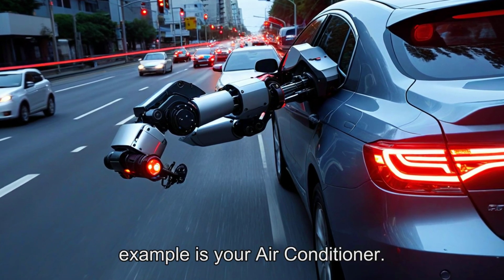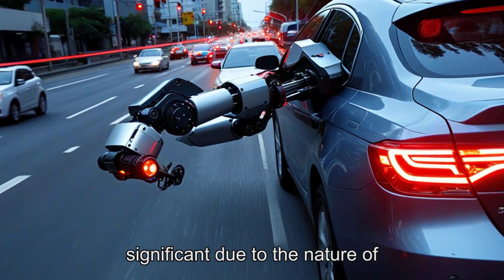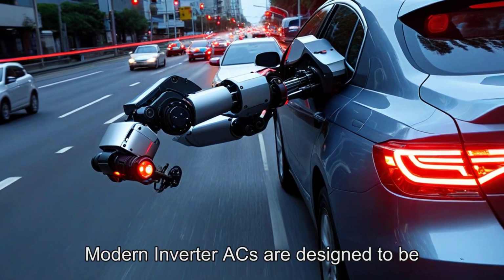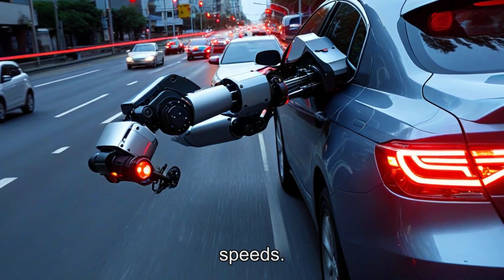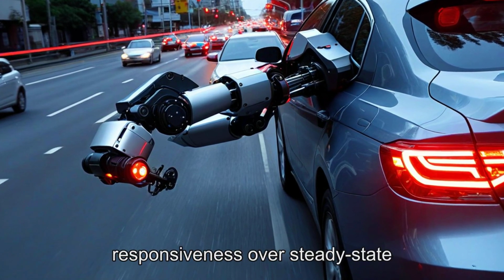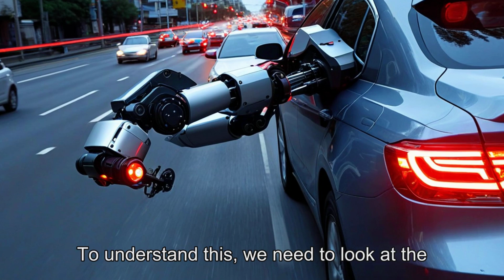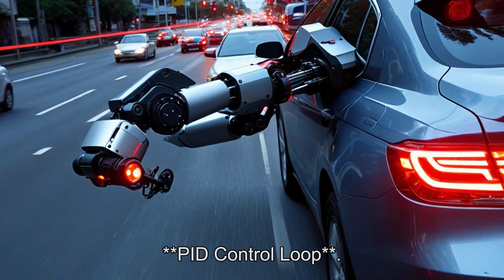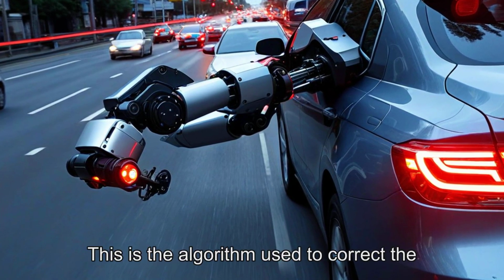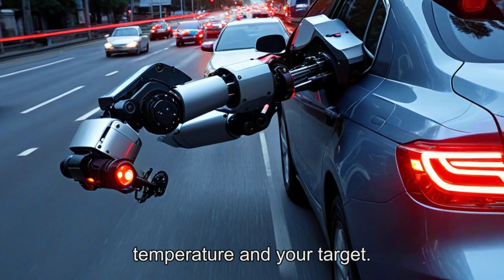The most critical example is your air conditioner. This is where the cost implications are significant due to the nature of compressors. Modern inverter ACs are designed to be efficient by running at steady, low speeds. However, auto mode often prioritizes responsiveness over steady-state efficiency. To understand this, we need to look at the PID control loop. Proportional integral derivative. This is the algorithm used to correct the difference between the current room temperature and your target.